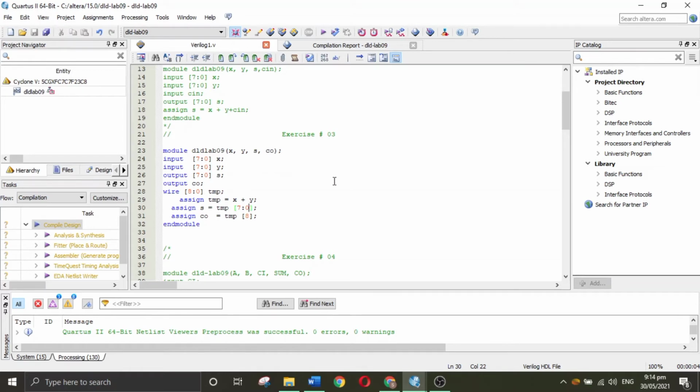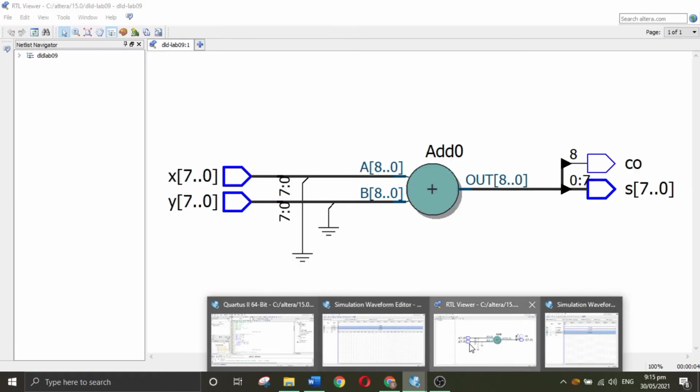So here you can see that if we add, for example, a 4-bit number, and the sum exceeds the 4-bit value, then it may be 5 bits. So this is the necessary condition to put the wire in a wider value, so as to divide it into the 8-bit, and the 9th bit is this. Actually this is 9-bit, sorry for that. These are 8-bit values and this is the 9-bit. So the 9th bit will be the carry output.